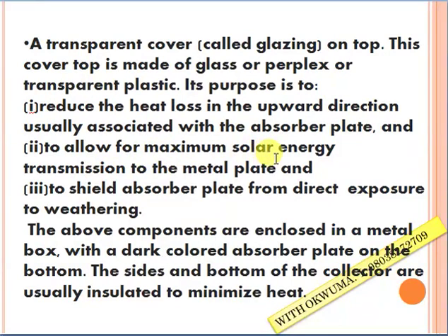Since it's transparent, energy from the sun can pass through it. Rays of light from the sun pass through it and get to the absorber plate. So it allows for maximum solar energy transmission to the metal plate. And the next one, finally, it can be asked in the exam or WAEC. State 3 functions of this transparent cover, or called the glazing cover or top.